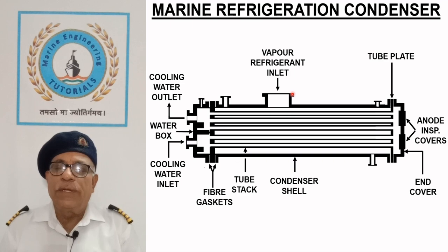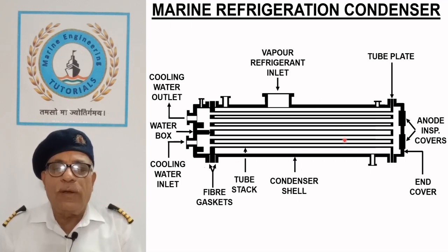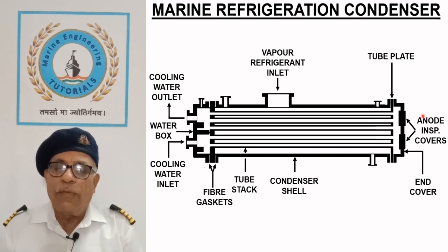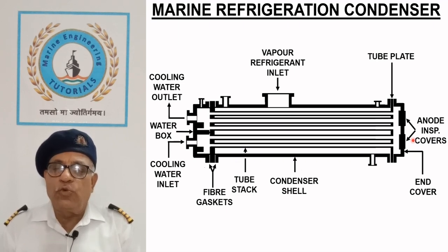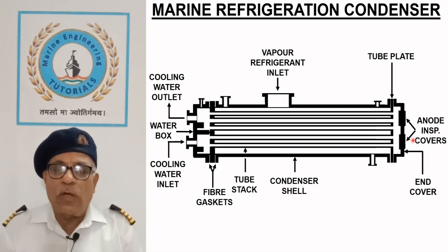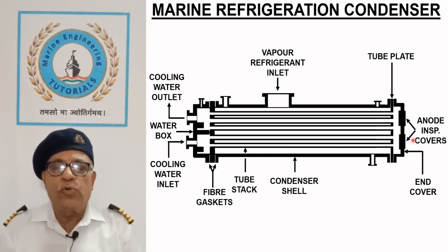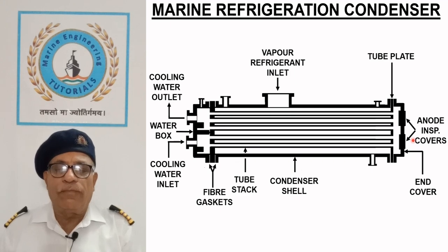Water boxes were prevented from corrosion by sacrificial zinc anodes earlier when seawater was used as coolant. Presently, treated fresh water is used as coolant which does not require regular cleaning of the condenser as compared to seawater system.